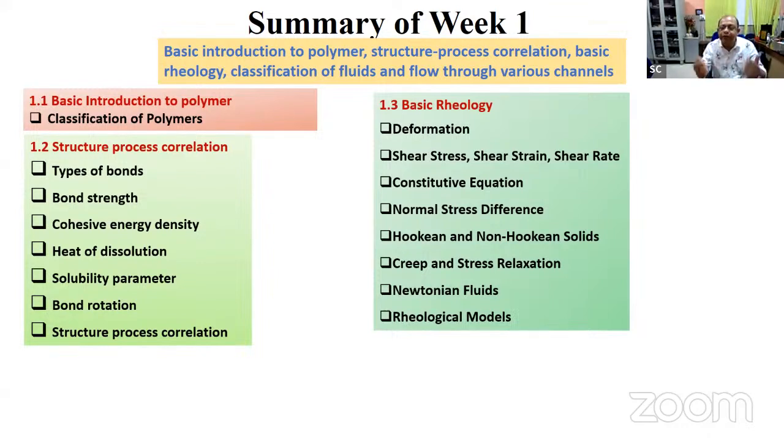One, say for example, can be quasi-static type, say for example, creep and stress relaxation experiment. Another one is a dynamic one, which is a directly dynamic mechanical properties that I emphasize separately. Okay, I talked about Newtonian flows, Newtonian fluids, and non-Newtonian fluids, of course, and several rheological models that depict a